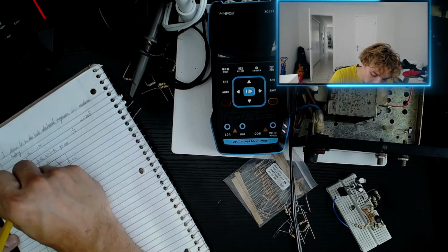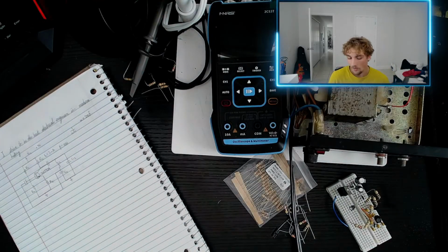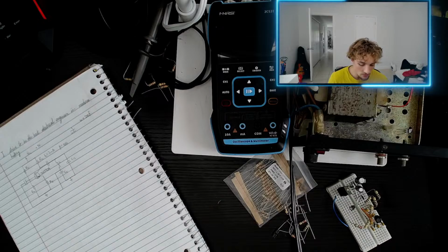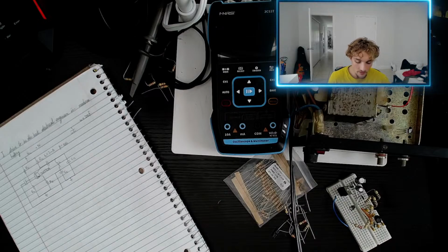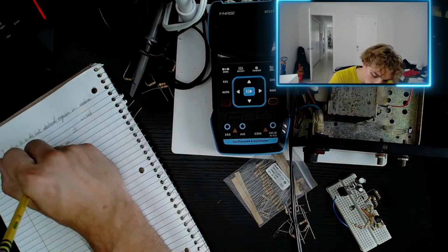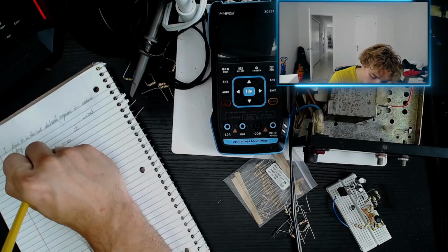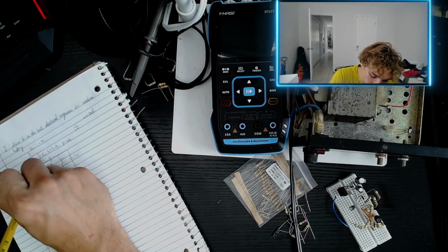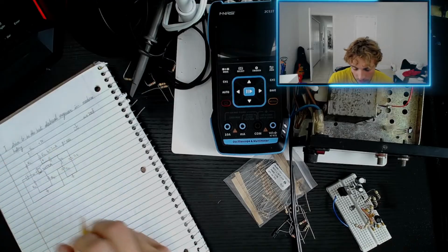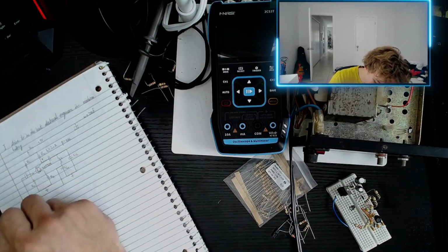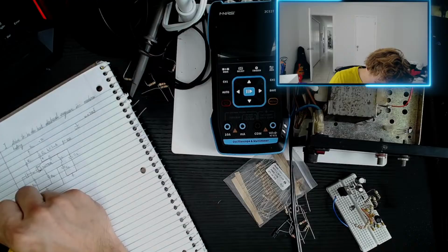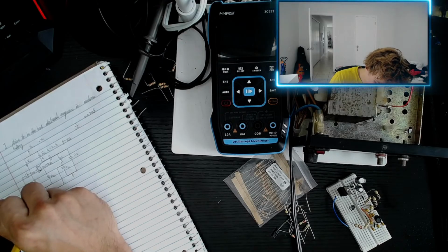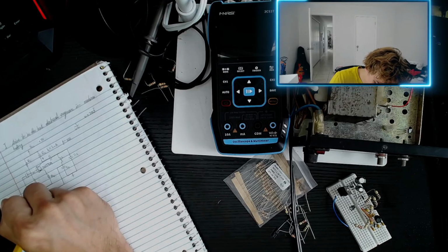Therefore, the way that the NPN transistor operates is that it operates on current, right? So if we have a gain of 100 and approximately 2 milliamps flowing at the collector, then our input into the base of the NPN transistor is going to be IB equals 2 milliamps divided by 100.